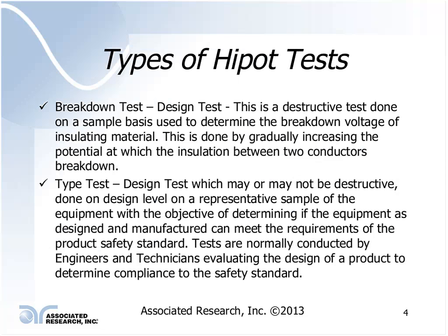Depending upon the type of material, the application may vary a little bit, and the specifications that you're actually testing to. If you're doing dielectric oil withstand testing, that might be done to something like ASTM D877 as an example. If you're doing solid dielectric material testing, that might be done in accordance to ASTM D149.